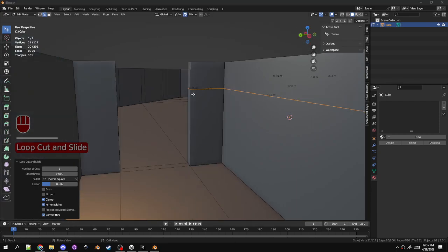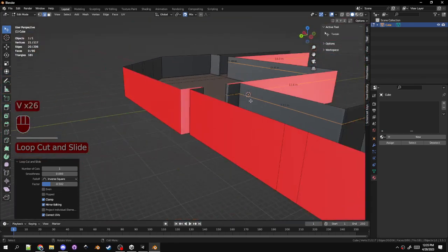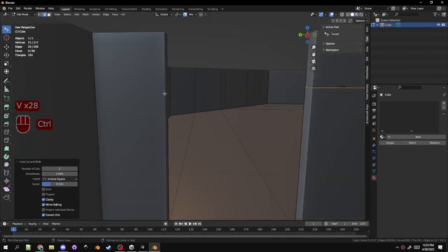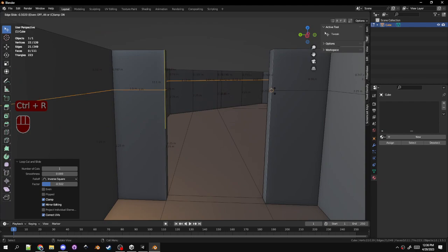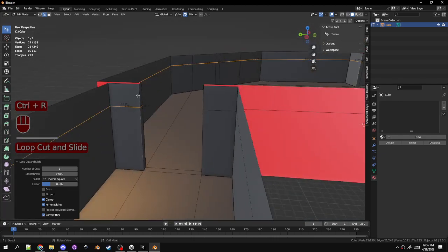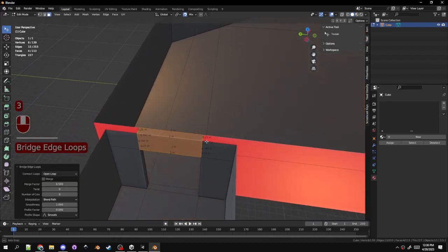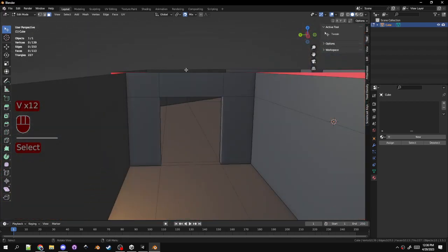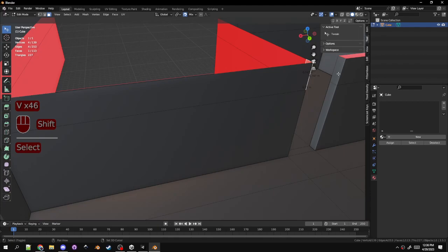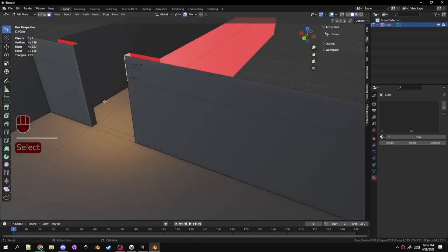So doors are 2.25 meters tall, I think. Yeah. So here we have all the doors have the 2.25 on top. I'm gonna do the same thing for this left side. I can vertex snap it to the right one, and then what I can do is I select both these and click bridge faces, and bam! Now we have our door head, up above the door frame. And then we go through door frames, click bridge faces. We do that with all the doors.